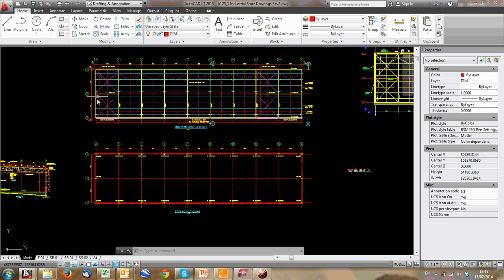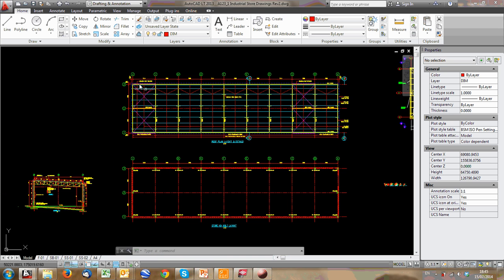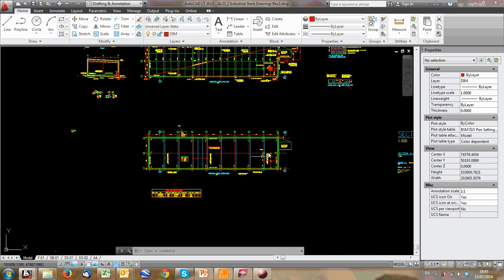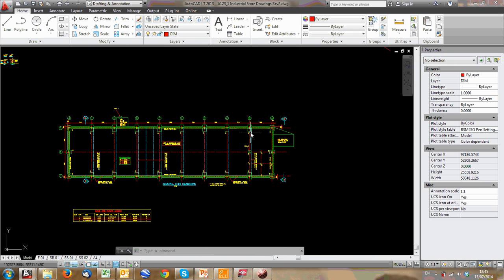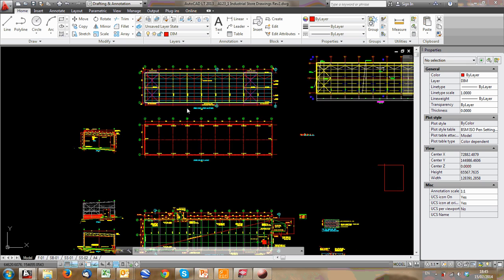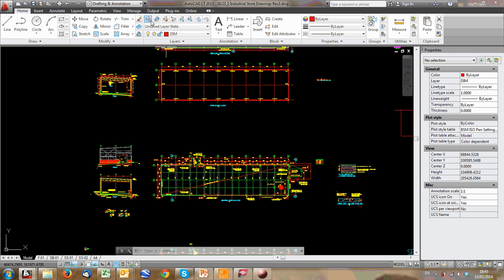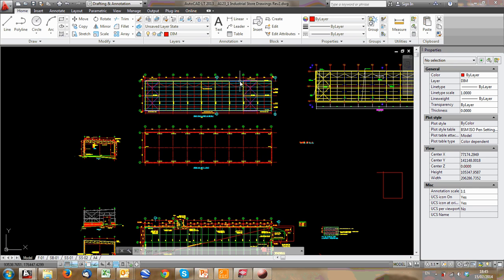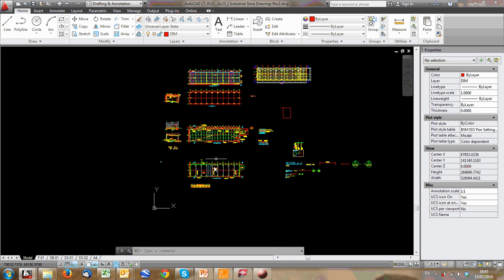What we're going to do now is take this layer, or this whole roof layer, and drop it on top of our foundation layer, just to make sure our columns are in the right position, column sizes are correct. But you could do that with a lot of things. You could do that with surveys, you can do it with mechanical engineers' layouts, architects' layouts, etc., where you overlay one drawing on top of the other.